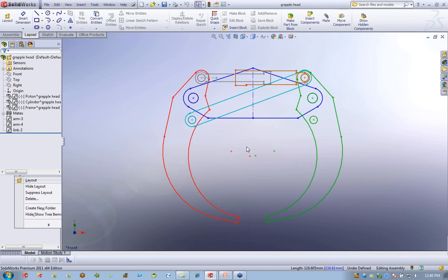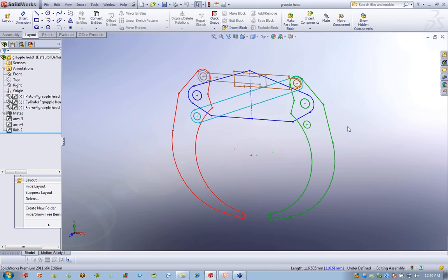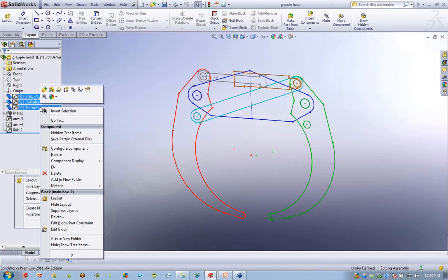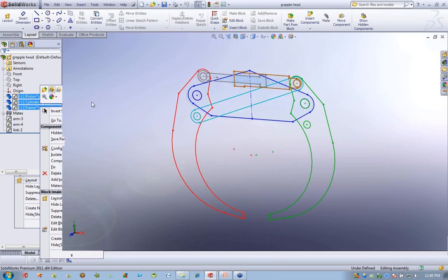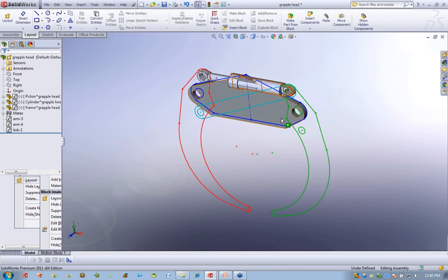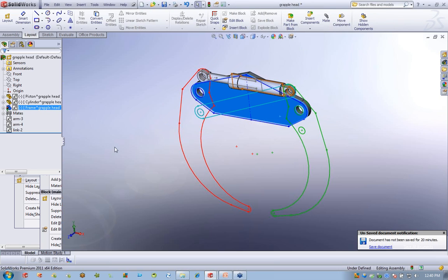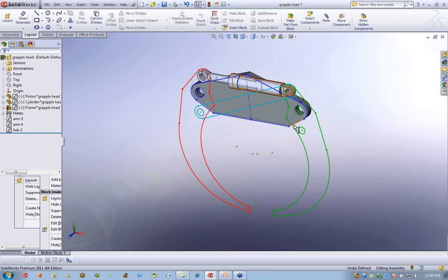Now I wanted to show you an example of an assembly, back to the assembly environment, using the projection technique. When you project a sketch block, it is not restrained to the plane where the block is tied to. And I have some examples here. If I go ahead and show these parts that already exist, we have kind of a backing plate where everything's going to be attached to in a cylinder here. But I need to take these arms and turn them into a solid model.